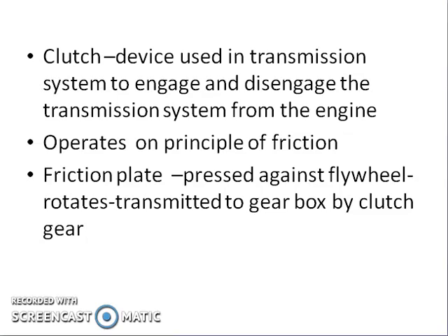So in all these cases, we preferably try to disengage the transmission system from the engine. For this particular purpose, we are using the clutch. So a clutch is a device which is used to engage and disengage the transmission system from the engine. There are many types of clutches and we are going to see clutches which operate on the principle of friction. The friction principle is very simple.